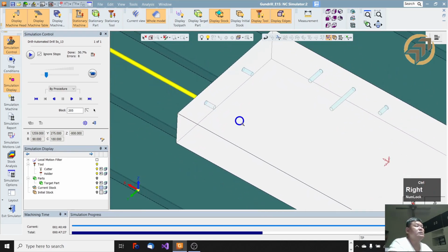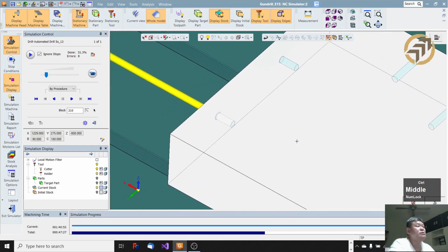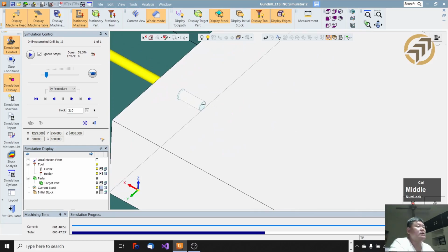And at this stage, you can slow down the feed rate to enter the pilot hole, down to the pilot hole depth here. Then when you're at the end of the pilot hole, next is to machine a 5 mm guide. We call it guide, and you can machine this guide with, for example, 50% of feed rate.